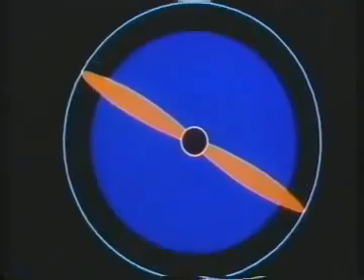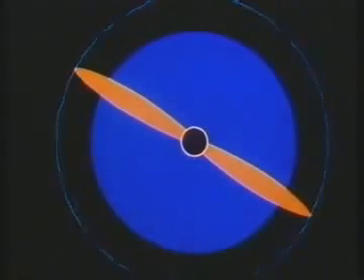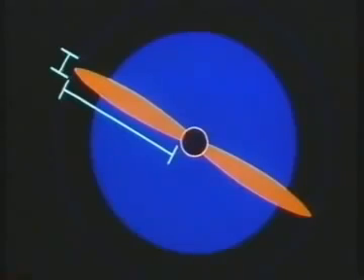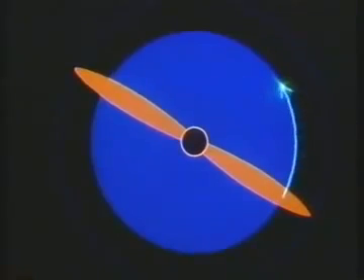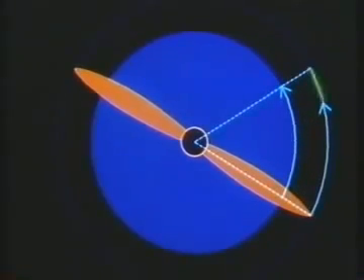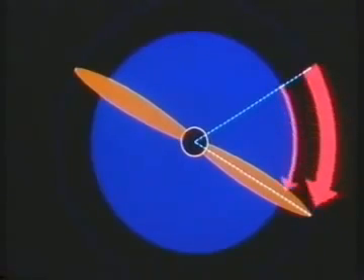Firstly, the diameter can be increased. This enables an efficient high aspect ratio blade shape to be maintained, but increases the tip velocity, which is of critical importance, since compressibility effects at transonic and supersonic speeds greatly increase drag, which reduces the propeller's efficiency.